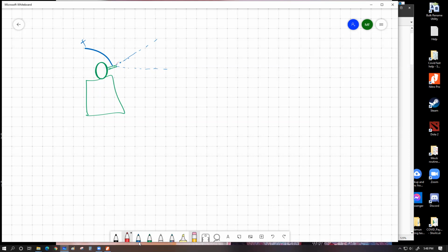I'm using red to show you the difference. So the angle of spread would become wider naturally, irrespective of the design or anything, because the paint droplets, as they move out from this place, will repel each other. So you'll have a wider spray area. Make sense? Yes, sir, I got it. Beautiful.